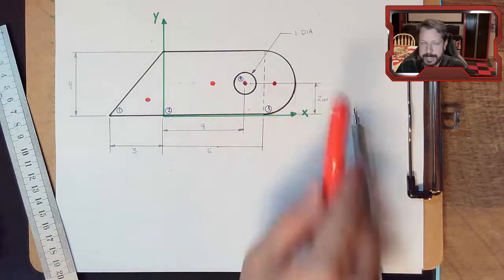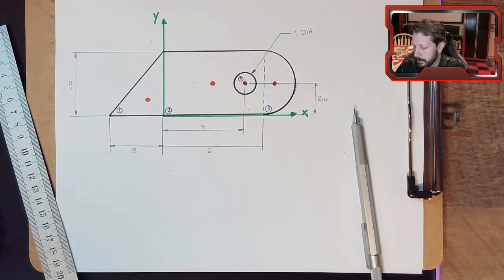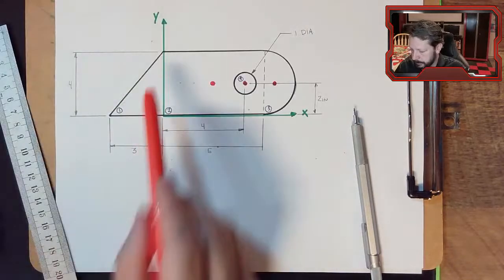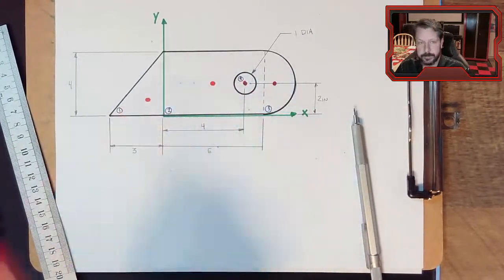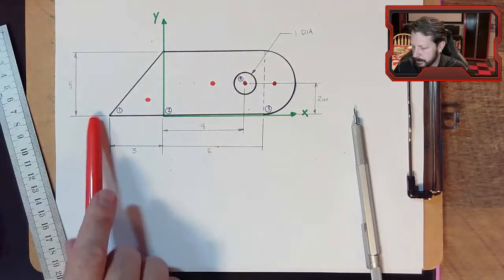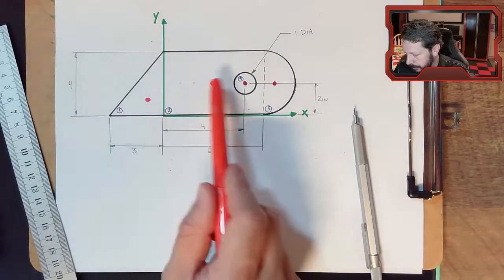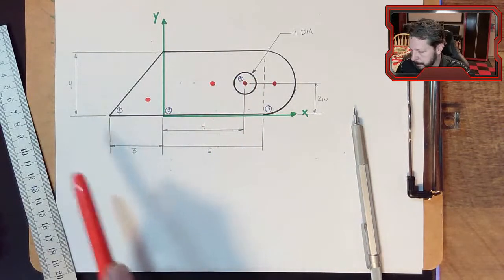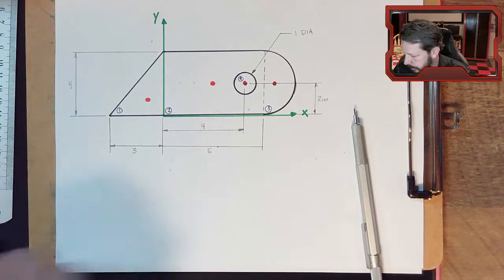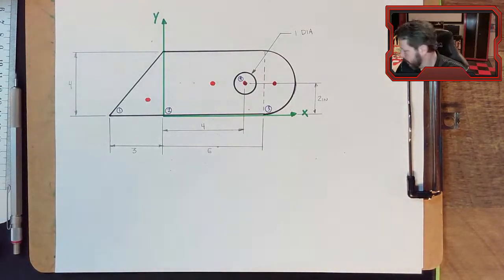And so I'm just kind of making guesses right here. And then I'm going to go in and actually use my charts to find where these individual centroids are, because our goal is to find the centroid of the composite shape, but you have to start with finding the centroid of the individual shapes. Remember, we're trying to solve the equation.